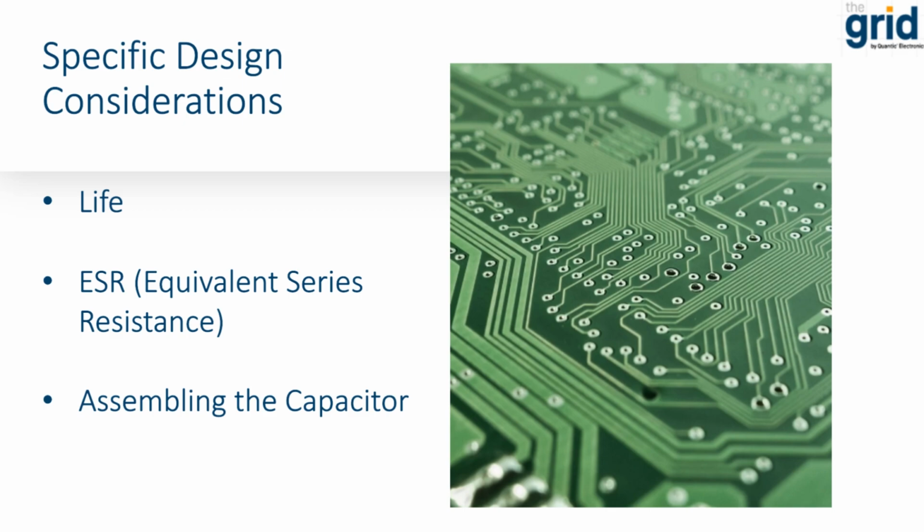Electromagnetic pulse, radar, and other similar directed energy applications work by means of a high current pulse. If the ESR of the capacitor is high, a lot of energy can be lost, typically in the form of heat. This phenomenon increases exponentially as the current increases, making these high current pulsing applications very sensitive to ESR.